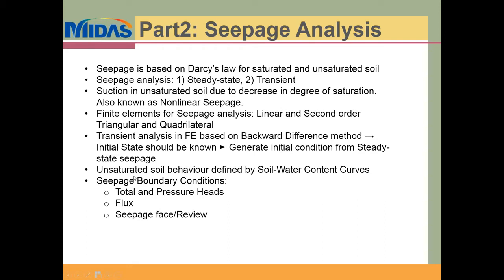And if you have unsaturated soil behavior, then it can be represented in terms of different soil water content curves. They could represent, for example, a relation between the relative permeability and the suction pressures. In the literature, there are different types of curves which you can use.